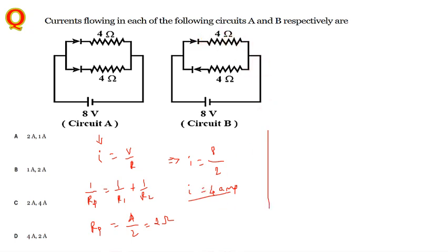For the second case here, again I is equal to V divided by R, and V here is the potential, again the same 8, and R here is only the one through which current will be flowing towards this direction. This is the reverse bias characteristic.